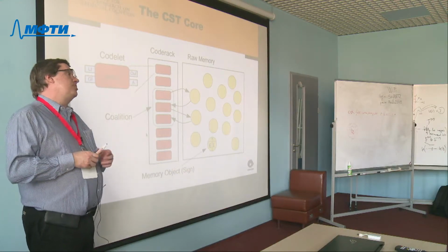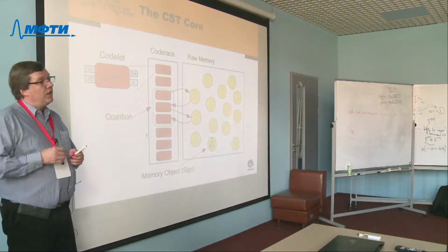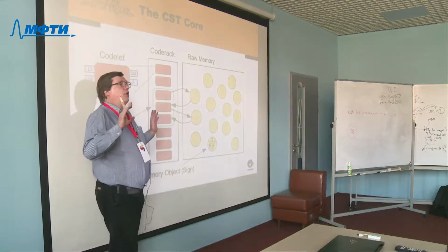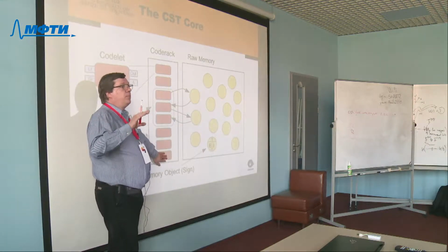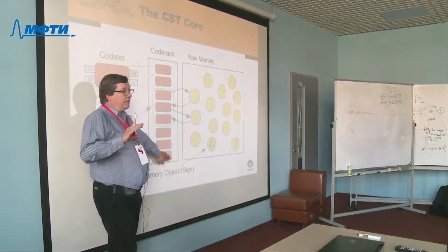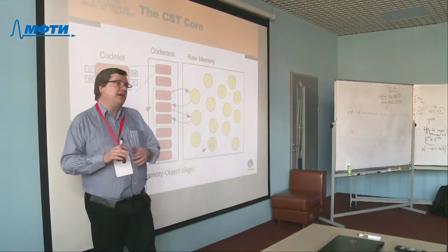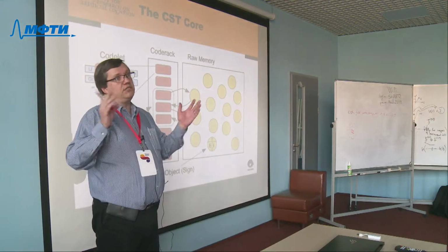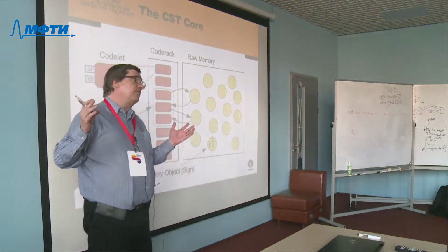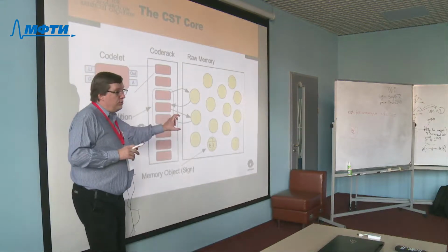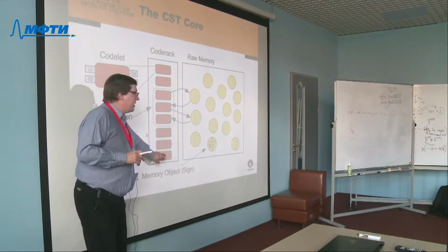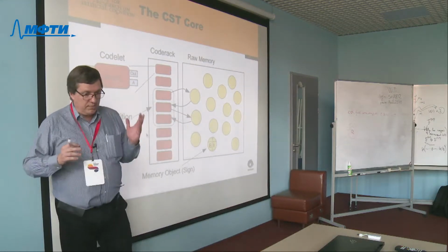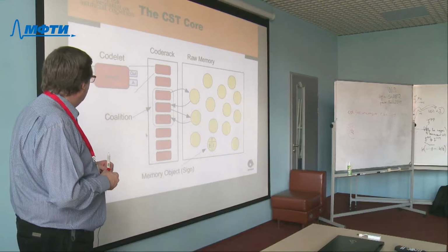There is also the possibility of profiling. What is profiling? Profiling is a way in which I start, okay, I don't know if it's enough or not, and then I put something to measure. And after this measurement, I realize that, oh, it's not going to work with 300 milliseconds because it is taking 700 milliseconds for operating, okay? Then with this information from the profile, you can change that to, let's say, 800 milliseconds, and then it will be able to do the processing that is required, okay?